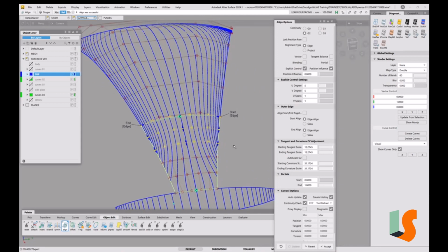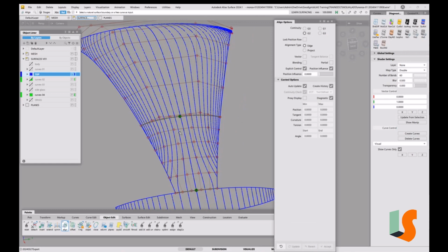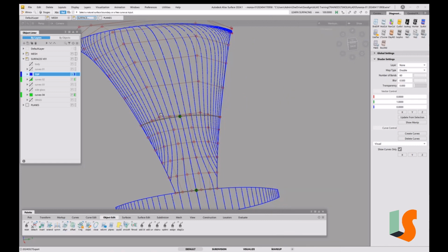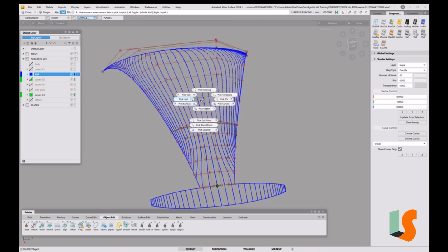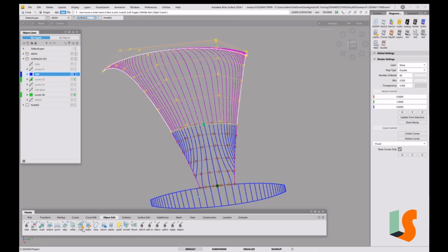Now, as so often is the case, we just want to move these CVs up and down in Z. We have the nice pattern in plan view. I just want to see what happens if I move those points up and down in Z. Because we're down to some refinement here, we want some mouse sensitivity on here, so I'm going to make it 50 to start with and see what we get. Now I notice that I haven't got symmetry on there, but keep your widths around value here. So I need to put the symmetry back on.